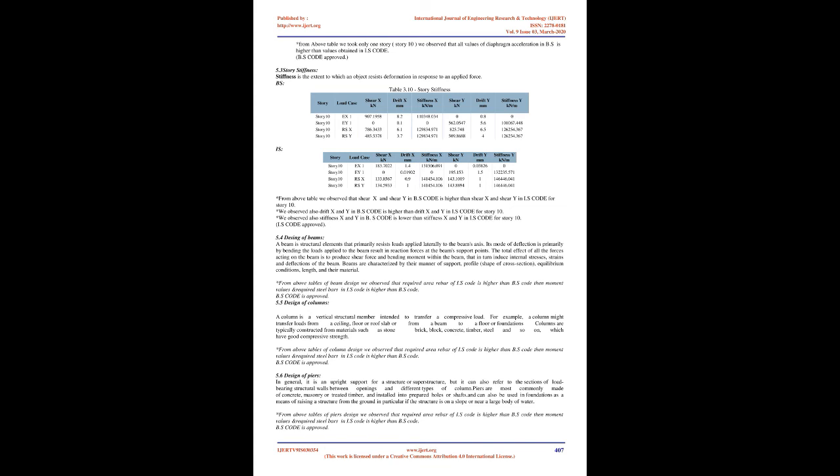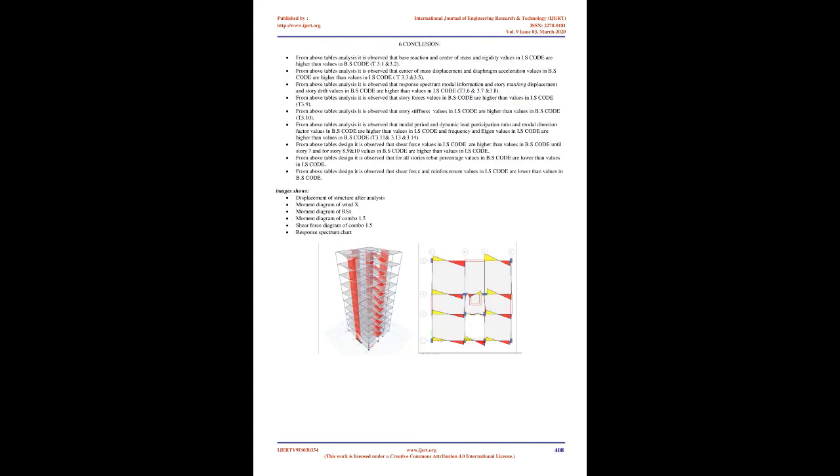5.4 Design of beams. A beam is a structural element that primarily resists loads applied laterally to the beam's axis. Its mode of deflection is primarily by bending. The loads applied to the beam result in reaction forces at the beam's support points. The total effect of all the forces acting on the beam is to produce shear force and bending moment within the beam, that in turn induce internal stresses, strains, and deflections of the beam. Beams are characterized by their manner of support, profile, shape of cross-section, equilibrium conditions, length, and their material.